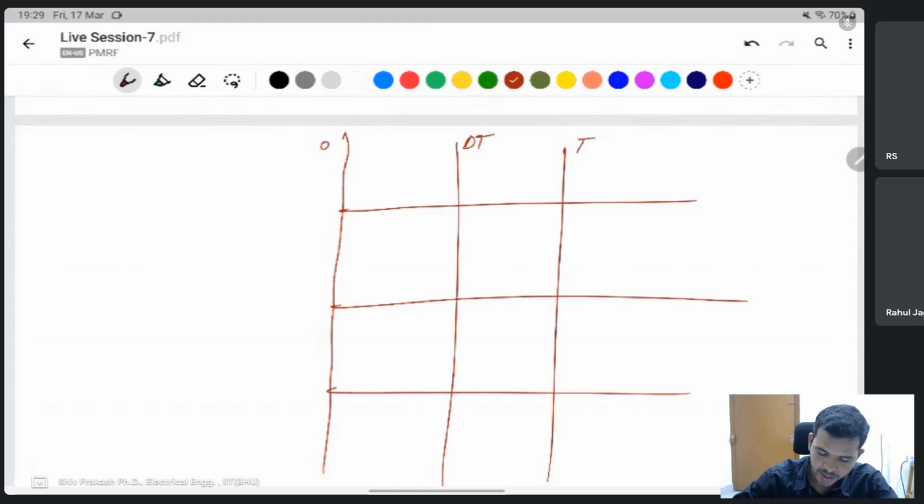DT is the on period, total time period T. The switch Q is applied from 0 to DT on period and then off. Then IL will charge from minimum to maximum, and maximum to minimum.